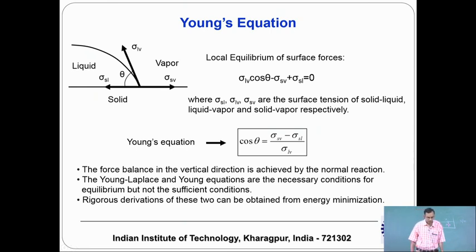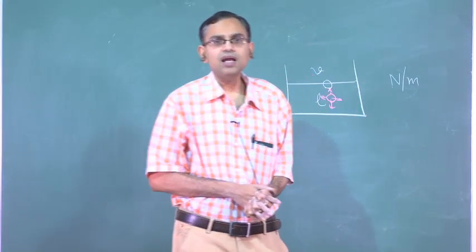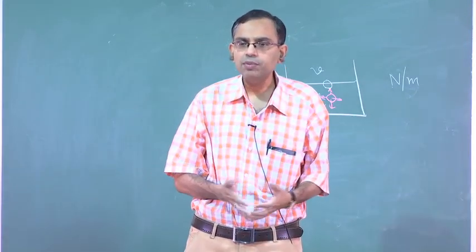For equilibrium the forces must be balanced in the horizontal direction, otherwise equilibrium is disturbed. So, you can write sigma LV cos theta plus sigma SL minus sigma SV equal to 0. It is a simple force balance equation, and that will give you Young's equation, cos theta in terms of the surface tension coefficients. Of course, this is a very simple derivation, but you can give a more rigorous derivation by using the energy minimization principle.